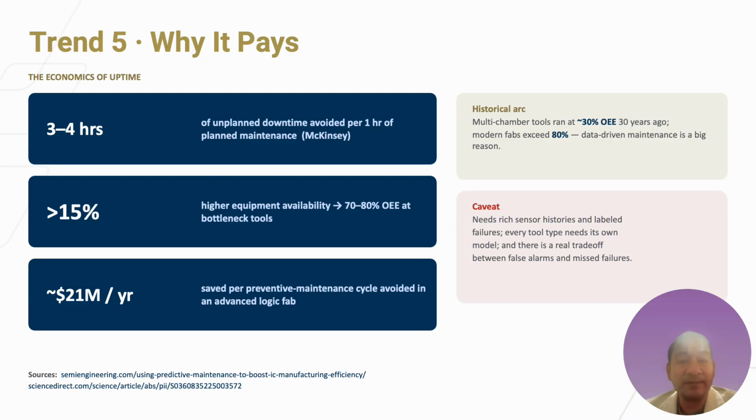Honest caveats: you need good sensor histories and records of past failures. Every tool type needs its own model, and there is always a trade-off between false alarms and missed failures.